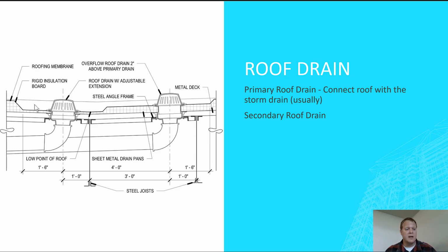But let's say, and this is super common too, and it's a challenge because you've got to sequence it, you get this roof done, and you've got the roof tied into this drain, and say the plumber's not on site, maybe he's got a little bit of a gap and you've got no piping right here, and you get a rain event. Well, the roof now collects a ton of water, goes right to these roof drains, and just right down, concentrated. Now, probably not going to damage a whole lot, because if you're just barely getting a roof on, you shouldn't have a ton of finishes down below.